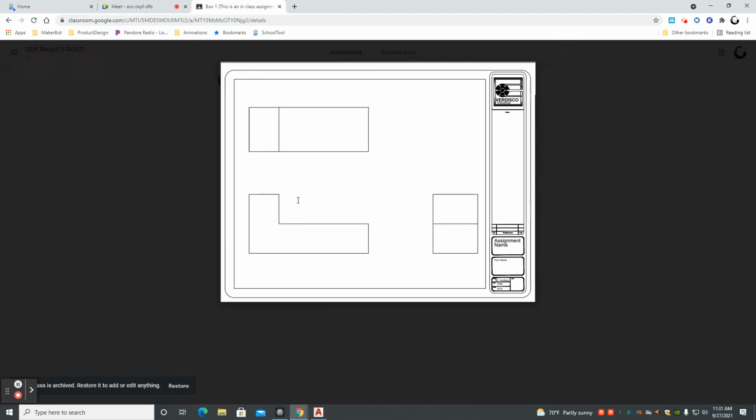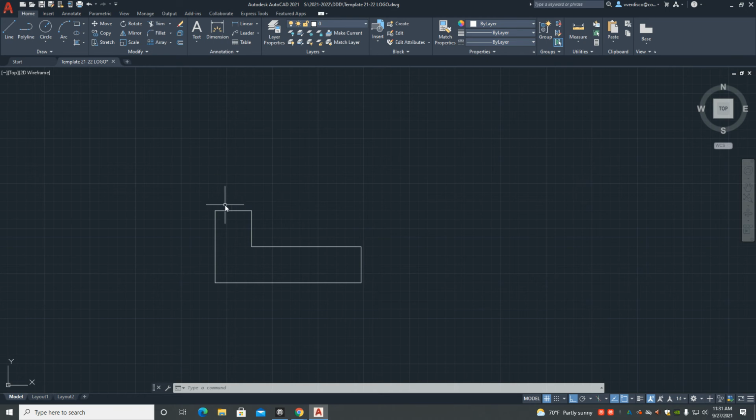So we're going to cheat a little bit. We're going to put a gap in right here, and then we're going to drag up some guidelines so we don't have to remeasure everything. So let's go ahead and do that. So the first thing is we said we were going to put that line in. So I'm going to go ahead and take my line tool. I'm going to go from here to here. Remember, this is 8, so I'm going to go ahead and put an 8-inch line in, just like that. Now, let's go ahead and offset that 8-inch line by 2 inches. So we have a 2-inch gap. Now, in the future, there'll be ways to measure sizes and stuff, but for this, let's just keep it simple. All right, so there's the line.